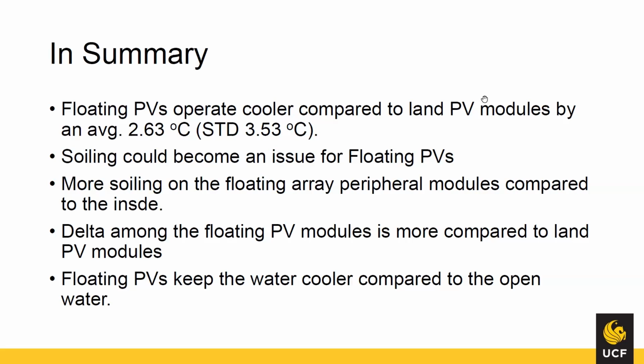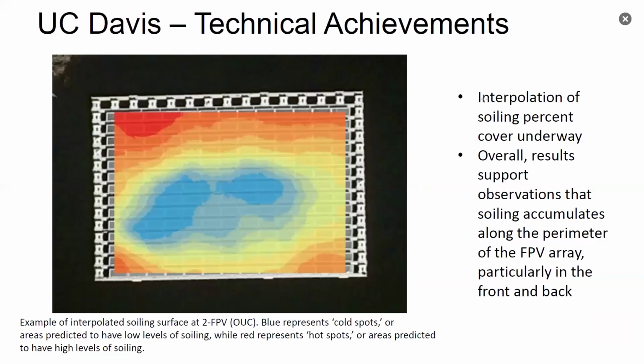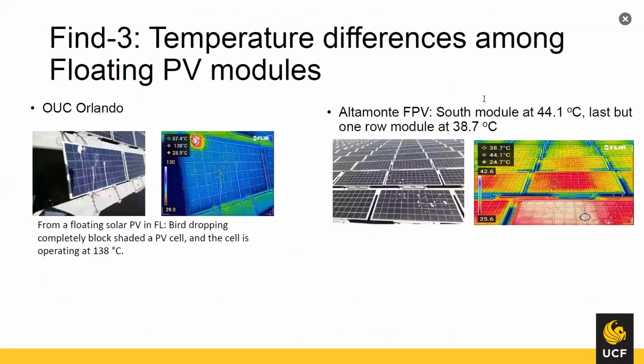The beauty of white surfaces is they're omnidirectional reflectors, so you can get some really interesting false positives with IR. Confirming with any other type of temperature sensor that's not visually based would be valuable.